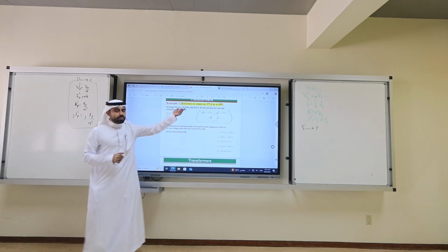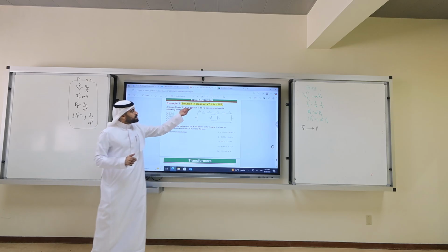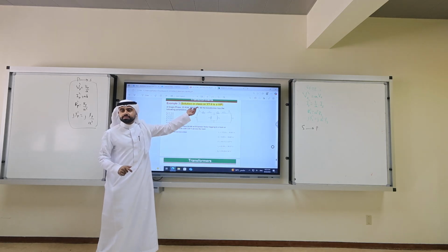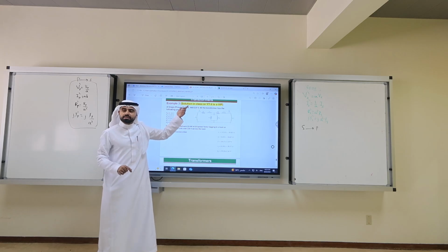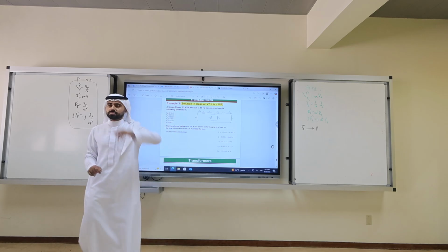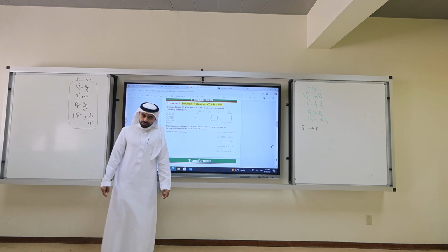This is apparent power. What is A? Turns ratio. Give me the number. What is the number A? Turns ratio: 440 divided by 220. Yes, 2.